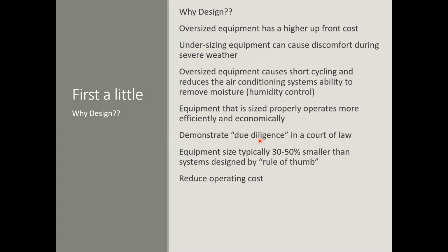Now, because this was a forced air system, I was then able to use Manual D to design my ductwork, knowing that I had my total equivalent length, all my static losses, and ended up with a friction rate that was between 0.06 and 0.18. So at least it had a chance of actually performing.